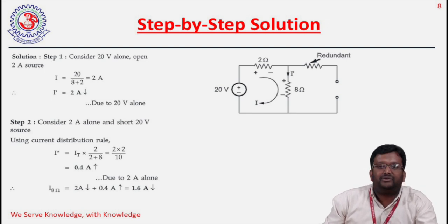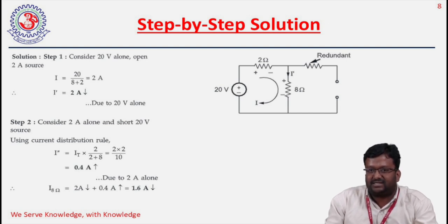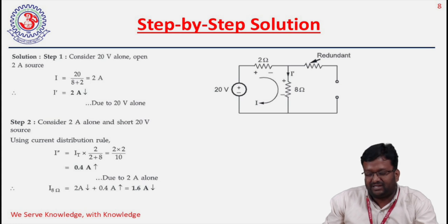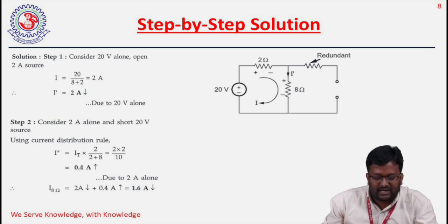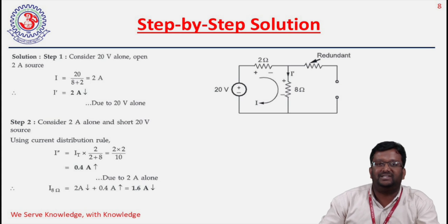Normally we apply series and parallel resistance formulas to find the equivalent resistance, because those methods are used to find the current delivered from an active source. But here the active source is a current source. We know the total current flowing from that source is 2 amps, so directly we can apply the current division rule.